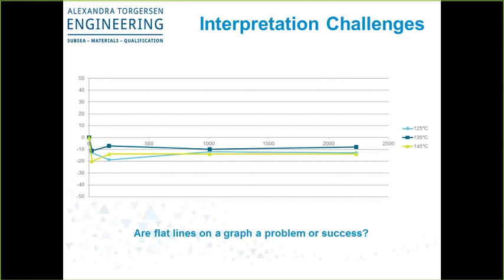And I think even in the oil field, indefinite is just a wee bit longer than we would be happy to claim our materials. So then it really does depend on how long you actually run your test for, if you can reasonably claim that you can extrapolate out to the service life or the material life of your particular material.